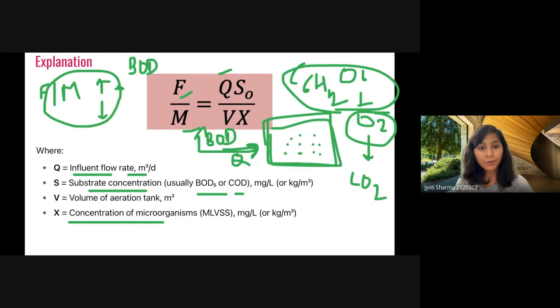Because ultimately, in secondary treatment we want to remove BOD, the organic matter, and we should have a sufficient F and M ratio. Should it be lower or higher to increase the efficiency of BOD removal? Can you write in the chat box, or speak a little about this? Should this F and M ratio be higher or lower to increase the BOD removal efficiency?